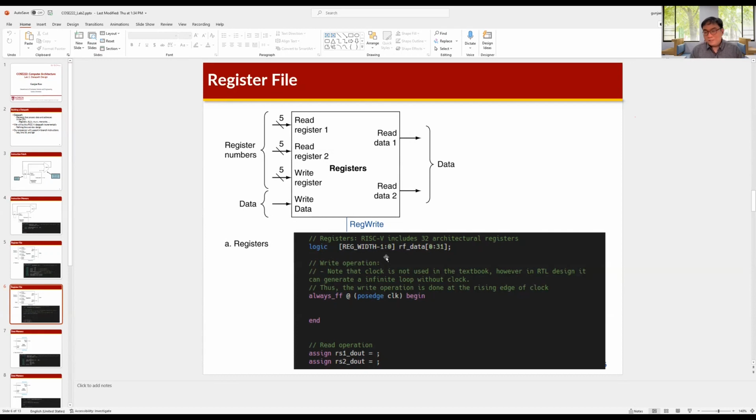But if the write data is not sampled by the clock signal, the register file is just combinational logic, so x1 plus x1 is repeatedly written to x1. So what's the problem? x1 becomes x1 multiplied by 2, and that is the new value.